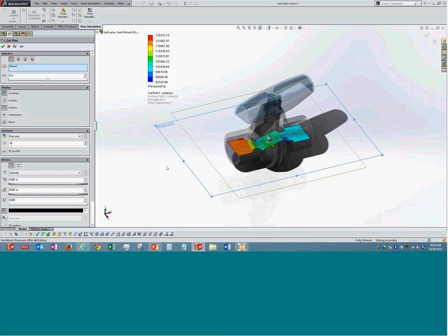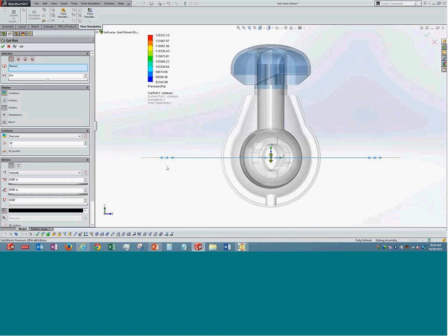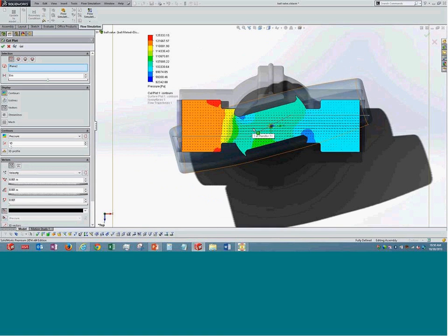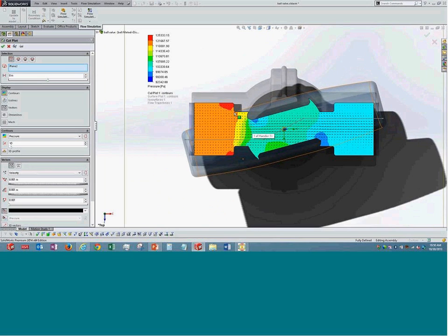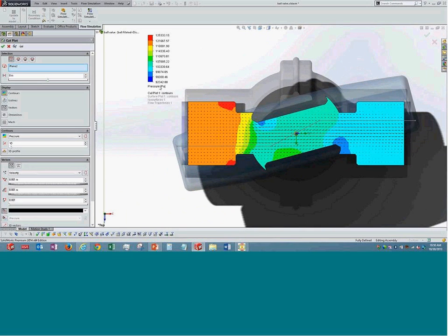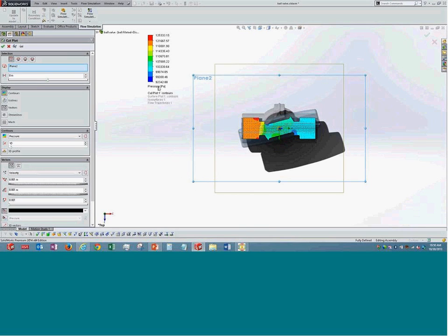We also have the option of ISO lines over here. We can remove vectors and see them. It could also be the streamlines, which are very interesting. Now, when I zoom in, the lines are increasing, showing us a more detailed view of the movement. This is dynamic in the sense I can hold this and move manually to see the results across the thickness of the cross section.